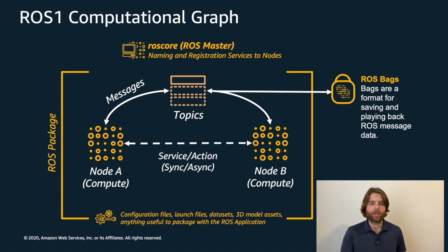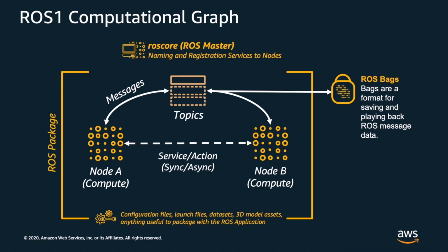And then finally, ROS bags are a data format for saving and playing back ROS message data. You can enable a ROS bag recorder that will capture messages that are being published over your ROS topics and then store them in ROS bags for later replay.